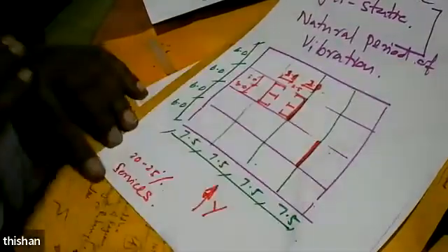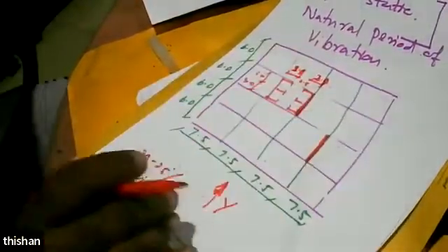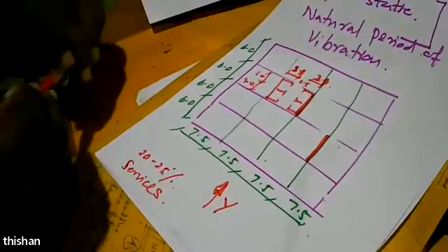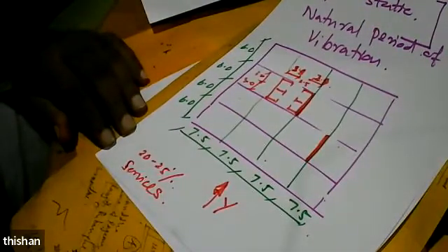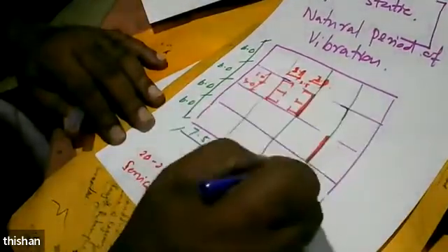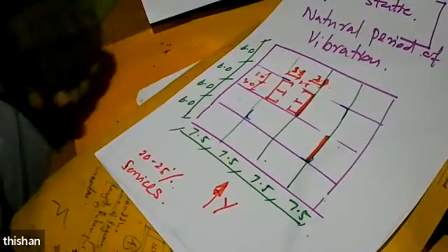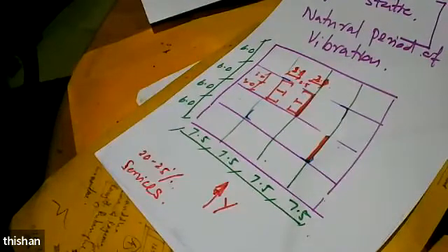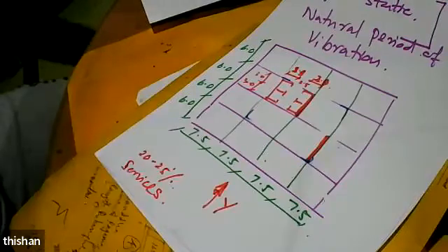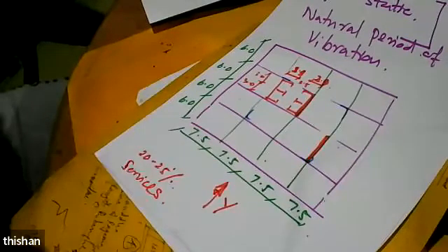So if you consider this building, how many panels are there? 1, 2, 3, 4, 16 panels. And if you want to have 25% of the area, how many panels do you lose? You lose 4 panels. So this area will be the core, 4 panels, 25% of the area. And you'll ask, why 25%? Can't it be 10%? No, it's not possible. A very good architect might get it to around 22, 23%. A bad architect might get it to about 27, 28%.